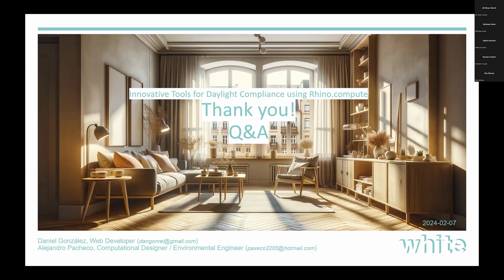Do you guys know Hops? So I think Hops, the plugin, can be used as a local debugger for compute as well. Yeah, so actually, I think Hops is the tool that I mentioned before that would cache the Grasshopper script, and that was a different approach. Andy told us about Hops, but we were already too far in the implementation of the solution, and we didn't invest the time in using Hops. But yeah, Hops is definitely something to check out if people are trying to do something like this. Yeah, Hops runs a local server. So actually, if your Grasshopper script works using Hops, you can be completely sure that it will also work in a web application or in another interface calling to compute.